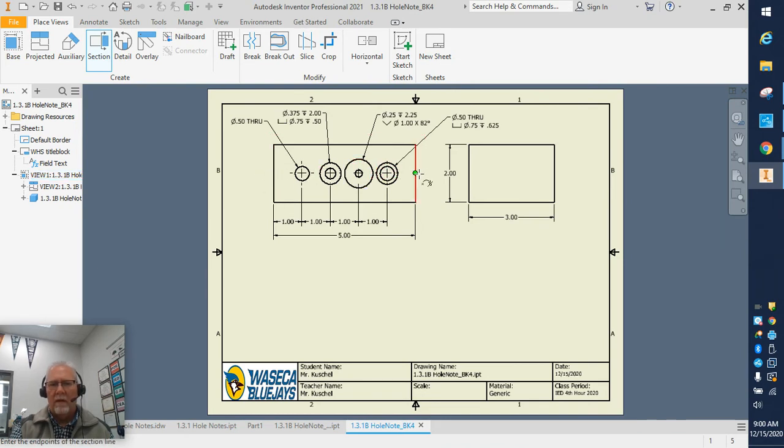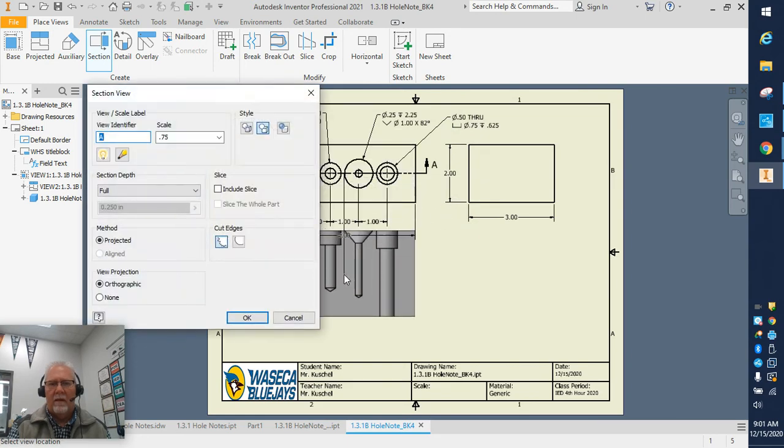And what we want to do is make a line all the way through. Now, I could easily click here, but you'll see in a moment that if I put that dot right there, it makes it hard to work with. So I'm going to put my dot out here, use my inferred point. So find that green dot, then move myself out, click, drag all the way through. It gets you a nice horizontal line. Click again, and now if I drag, it's doing some other funky stuff. I don't want that, okay? I'm done. If I right click and I continue, there is my section view.